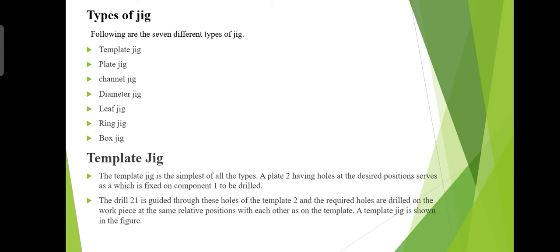If I talk about the clamp jig, which is not mentioned here, I will tell you something about the C-clamp jig. This device is named from the fact that it resembles some form of clamp. It is adapted for use on workpieces on which the axes of all the holes that are to be drilled are parallel. Clamp jigs are sometimes called open jigs.